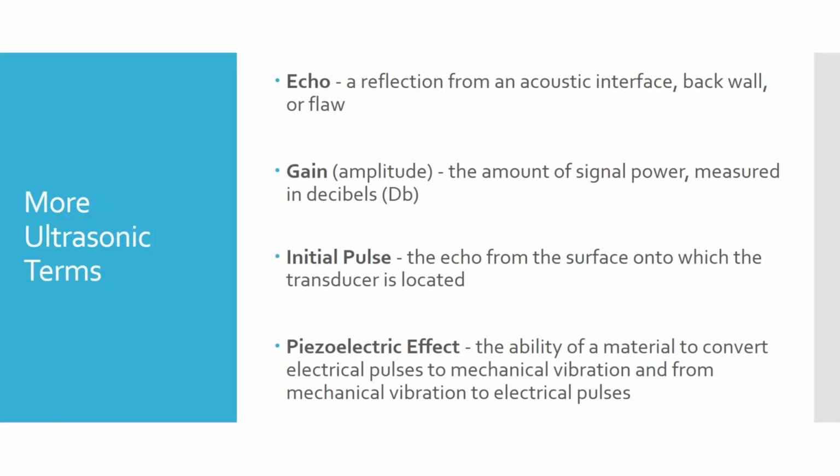The other way is, on some testers, rather than doing pulse echo, we can take two probes, and usually they'd be identical, like the probe in my left hand, we have these in pairs, but I'll use this one because it's kind of similar. And so for this one, what we can do is put them on two sides of an object and send a pulse from one and receive it on the other. So one acts as a transmitter, the other one acts as a receiver, a microphone. One acts as a speaker, one acts as a microphone.